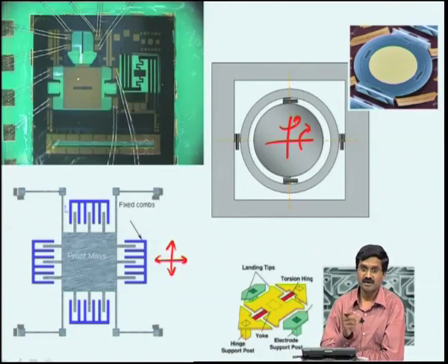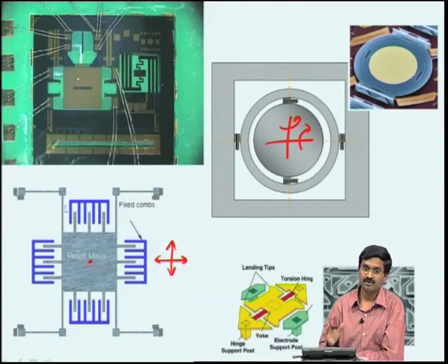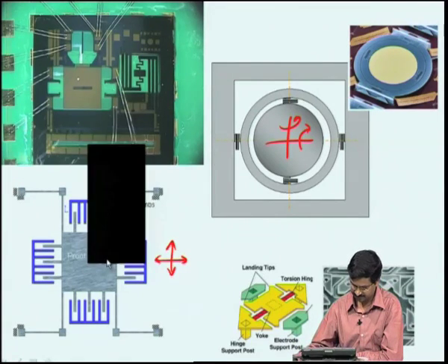The idea is we have to find M effective such that half times M effective times the velocity square of the point that we are considering, in this case could be the center of the proof mass, should be equal to the total kinetic energy of this system, and for K effective we take strain energy and get the equivalent lumped constants.